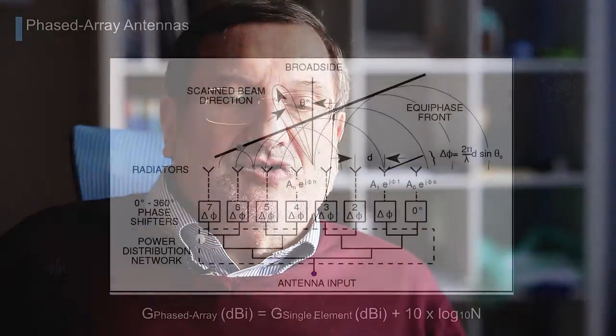The beamforming network being, first of all, a divider, a network that divides the input signal among the different feeds, and then through proper components we weight the phase, we change the phase, and this change of the phase is such as to change the orientation of the plane wave that is generated by the linear array. So we can orient this plane wave in such a way to get the beam oriented in the wanted direction.